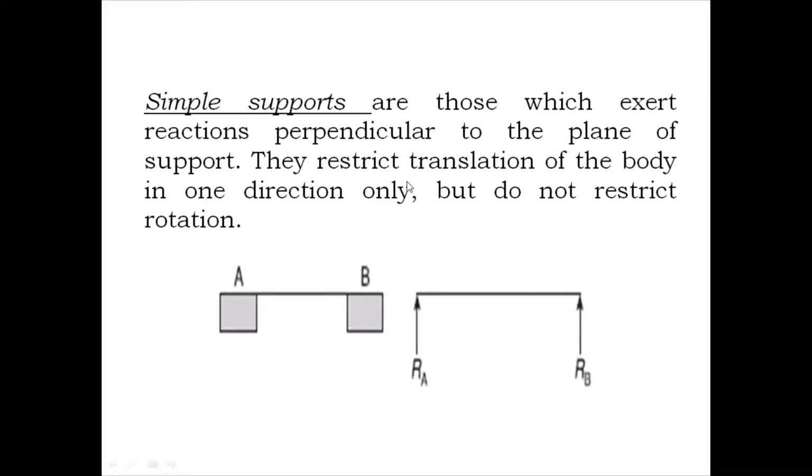Now, as you can see, simple support. What are simple supports? Simple supports are those which exert reactions perpendicular to the plane of support. They restrict the translation of body in one direction only, but they do not restrict the rotation.